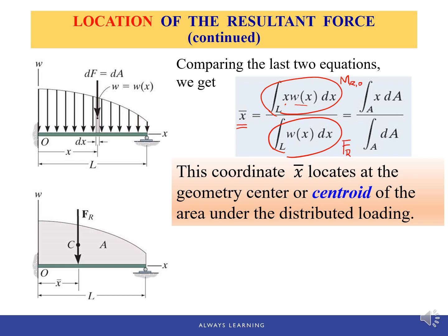Moment divided by force is the moment arm. In this case, this moment arm is the location of this concentrated load. And this coordinate x bar locates at the geometry center, or centroid, of the area under the distributed loading.